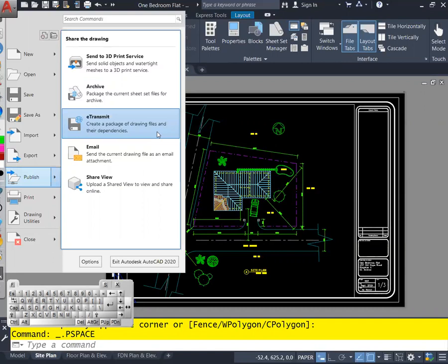If you don't have the plot style, the person... because what you're trying to do is to create a zipped up file, send it to somebody, and they should now be able to do everything that you were doing on your machine. Because remember, I told you that the plot style is saved on this machine. You want the plot style, and not only that, the page setup settings.